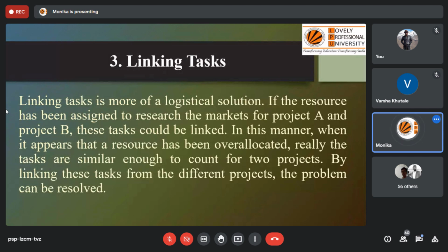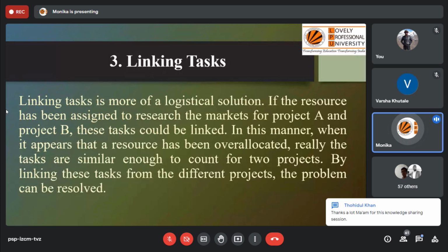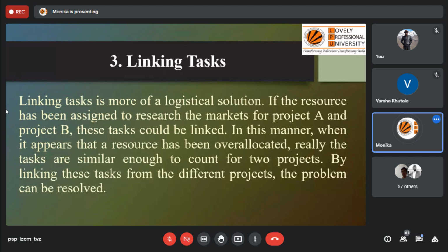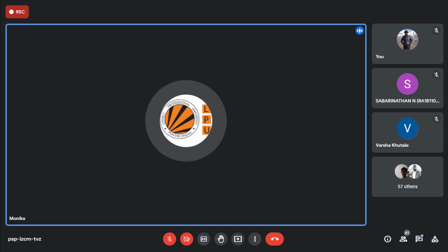Excavator, let us consider. In project B, the first activity is also excavation, going to start at 12 p.m. or maybe 2 p.m. Okay. And you are also writing there one excavator. Now it will show you two excavators are required. In your sheet, it will show two excavators are required. Now, let us consider you are only having budget for one excavator. All right.